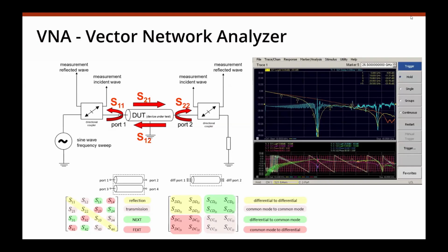So I would agree that part of VNA is more complicated, but if you go to a standard method like delta L, it's all defined, but you look at it, and at the end of the day, you would get an insertion loss going from front to back. In that case, that would be SDD21 that you would get out of a tool. So you would get one attenuation over frequency out of a tool, and then I would claim VNA is no more difficult than TDR.